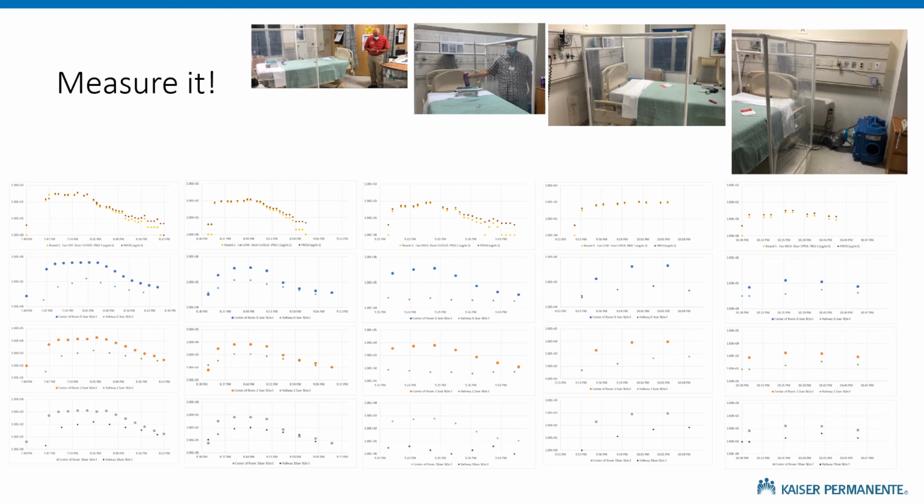We tested this with hairspray. You can kind of see me with a can there spraying it. When you put a can of hairspray at pillow height and then spray it out into the room, you're just contaminating the room. There's way too much velocity in that spray for the hood to ever capture it.